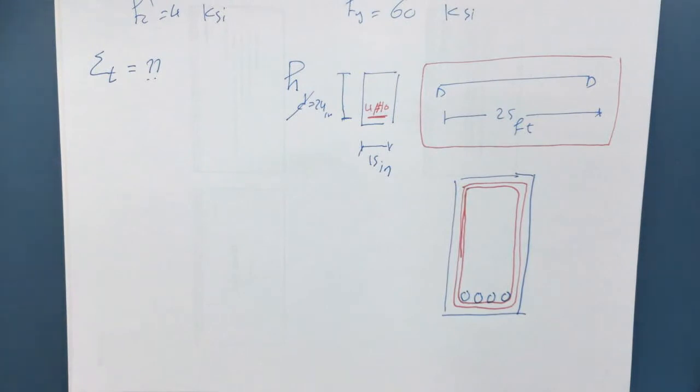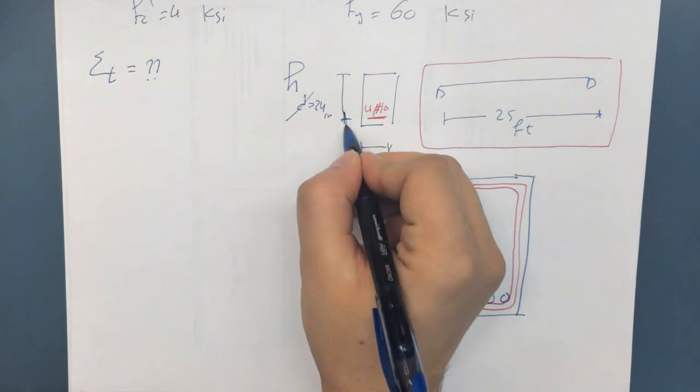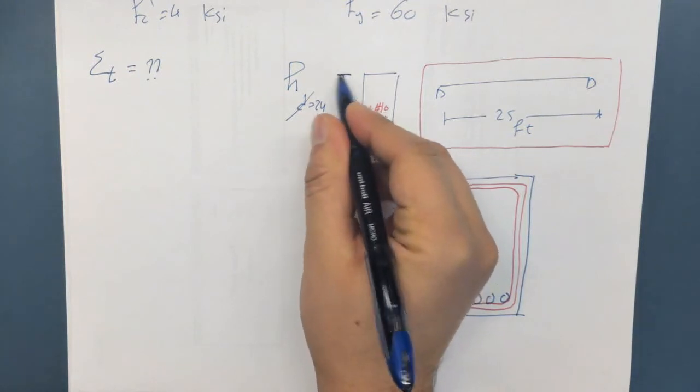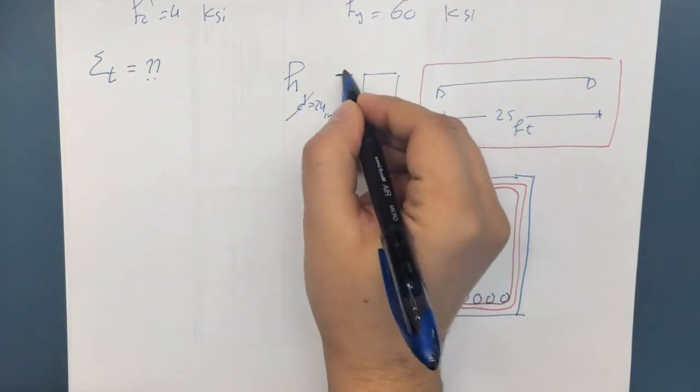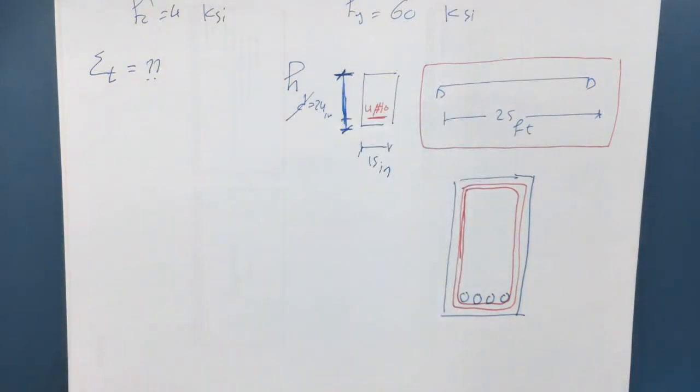And I think this is kind of misleading, because if you read clearly, you'll say the section depth. This is actually not the section depth. And I think it's going to be clear. This is from a training book. This is a section height. Okay, so the 24 inches in this particular problem, in this particular book, is the height. But it's not named as height.